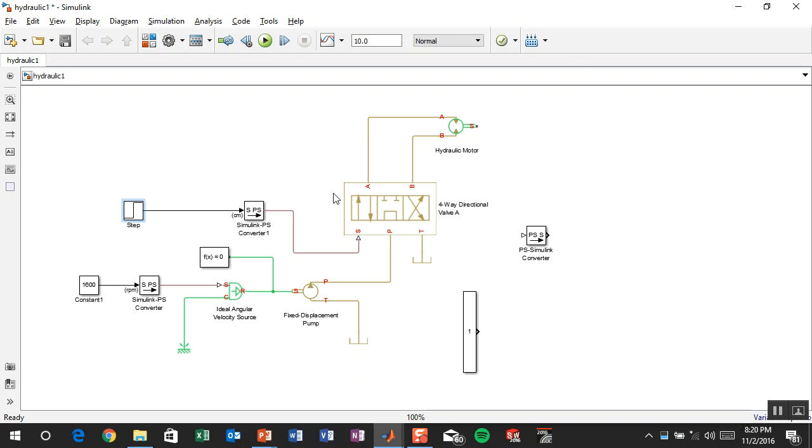Partially open. Does that model it? Yeah, and this is where you can dig down deep into the rabbit hole, because you can model your own valve, and all it really is is changing orifice sizes for a particular position. It's not rocket science, but you can make it do whatever you want.